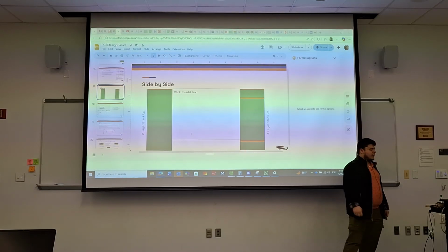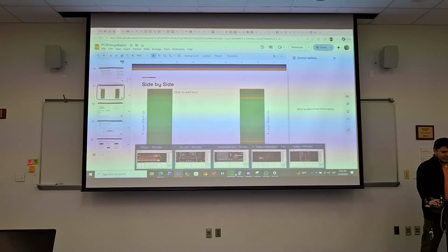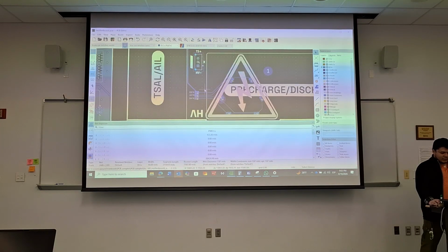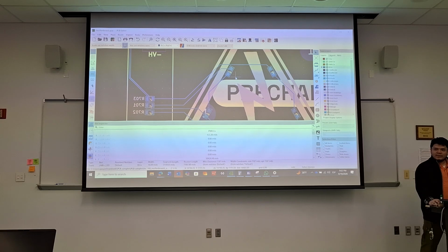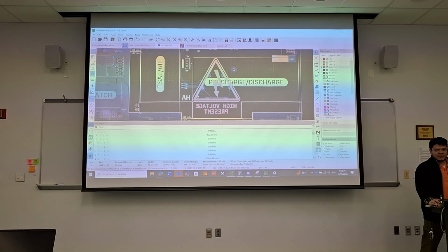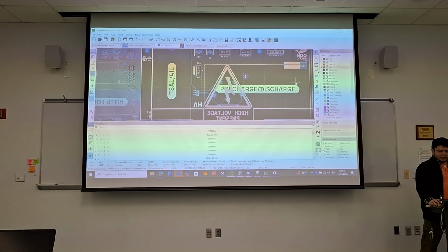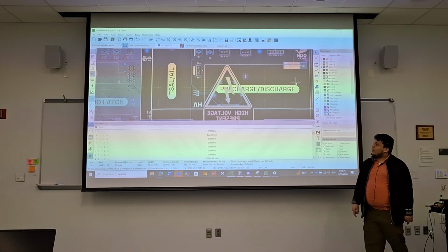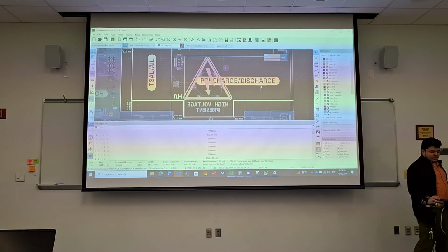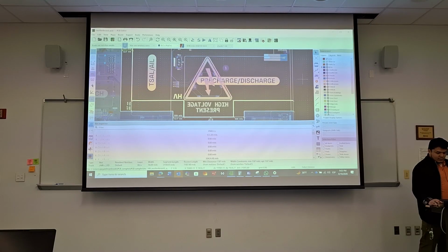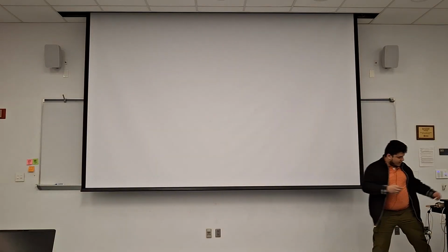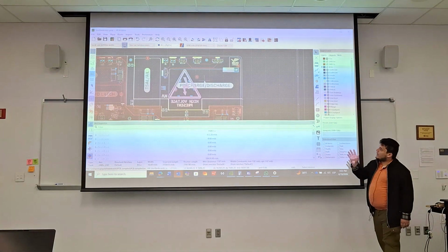Also, what's not helping, generally speaking, I don't think this voiding is helping you. I know why you're doing it, but then you also have these unshielded lines. And if anything, these are probably causing you the most headache. And I'll tell you why. You can get away with not having any traces on the first layer. And in this case, you have some traces. You can get away with those traces.